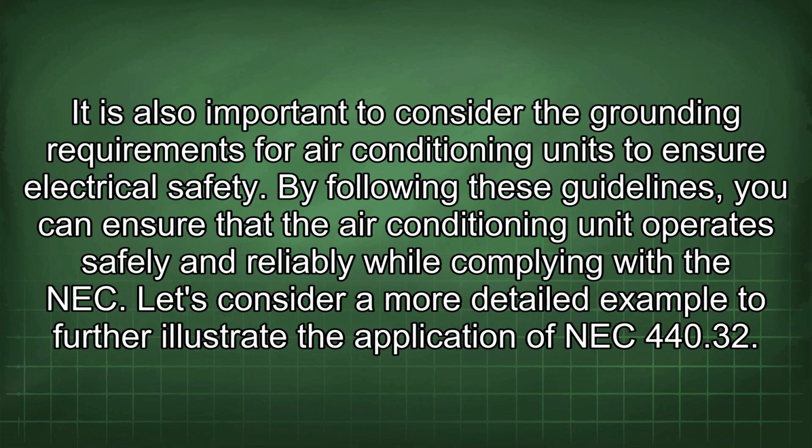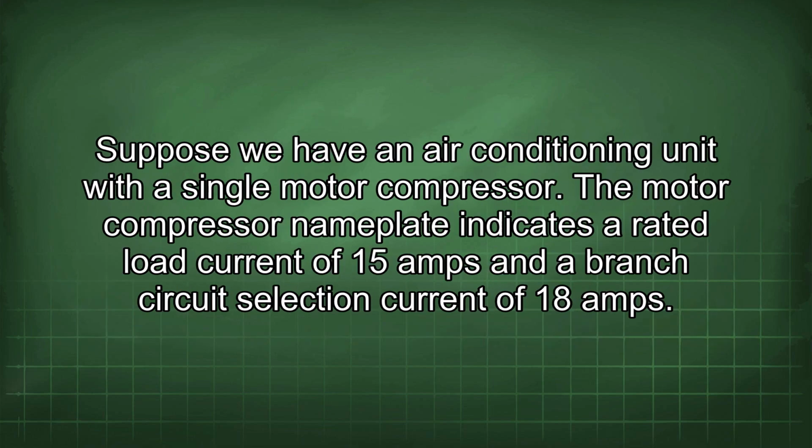Let's consider a more detailed example to further illustrate the application of NEC 440.32. Suppose we have an air conditioning unit with a single motor compressor. The motor compressor nameplate indicates a rated load current of 15 amps and a branch circuit selection current of 18 amps.